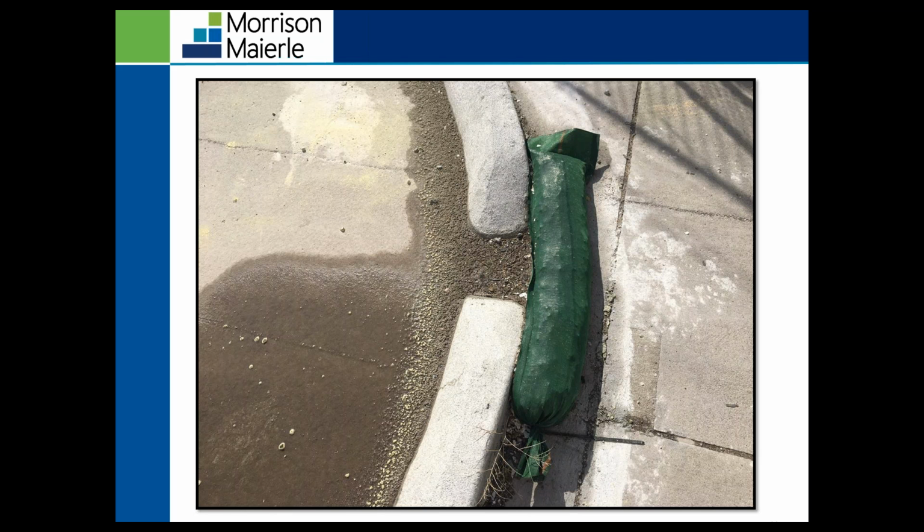It is important to know about this BMP that ponding can occur. It can get clogged and it won't allow water to flow through it. And you can even see right there on the left, you can start to see some ponding occurring. So you want to make sure with this BMP that you're maintaining it, removing that sediment, and inspecting to make sure that it's not clogged and not causing any flooding to occur, especially if it's flooding onto a public road.